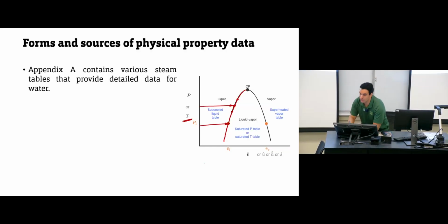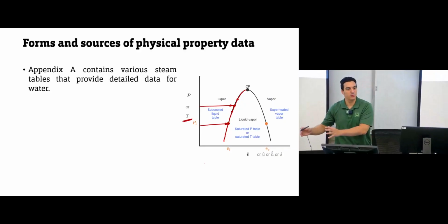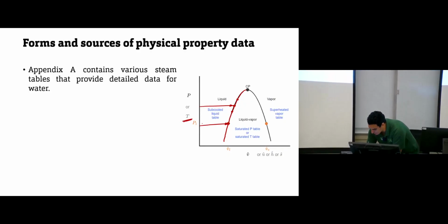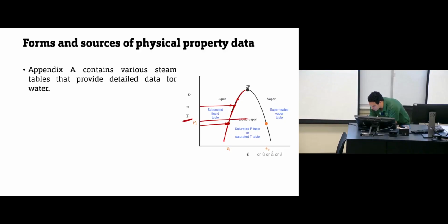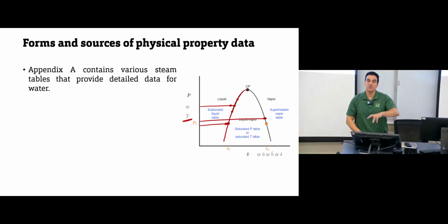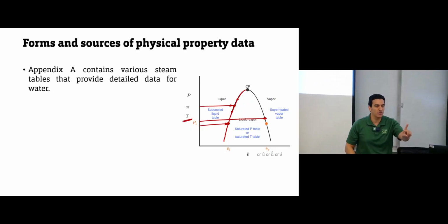So this is the saturated liquid at this temperature. Similarly for saturated steam, at this temperature or at any pressure, you can go to the other side. This will be saturated steam at this temperature or at this pressure. So just one piece of information is enough. Temperature or pressure is sufficient to locate the position of this point.